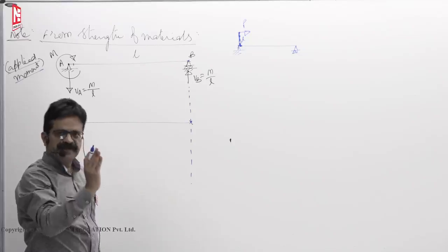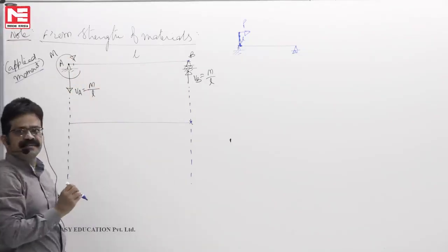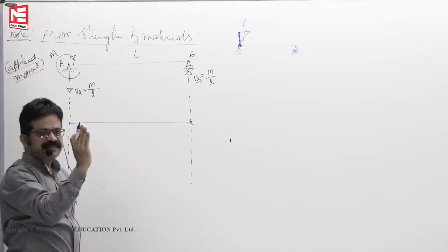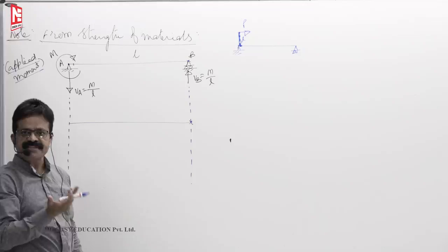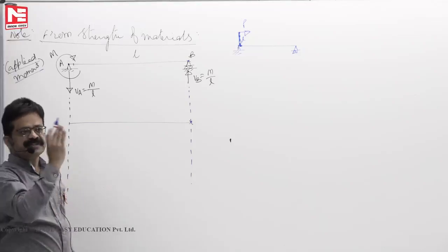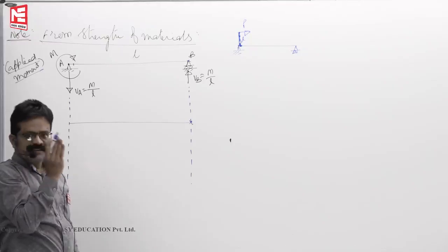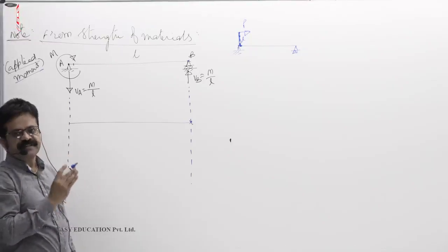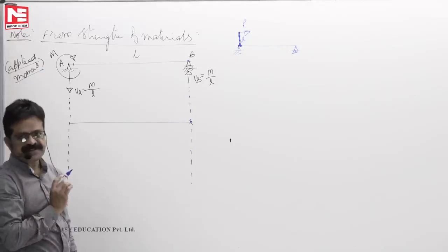When you stand exactly at the point where moment M is acting, and you put your leg on that moment itself, you do not know how much moment is under your leg, whether M or 10M. If you look at the right side you get one moment, and at the left side another moment. That is not called bending moment. Whether you look at the right side or the left side, you should get the same value. That's what you have studied.